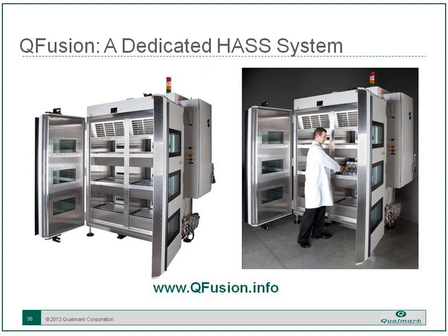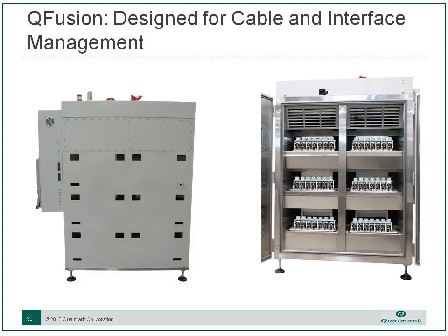Cable management and the interface card locations can become tricky. So what we've done on this chamber is we've provided dedicated portholes for each one of those levels that can be customized for any size and location across the back, so you can actually mount interface cards directly to the back of the chamber and then take those off to the functional test equipment. So when you have a chamber full of product that looks like this, you can have cards mounted on the back here and keep your cable management neat and clean.